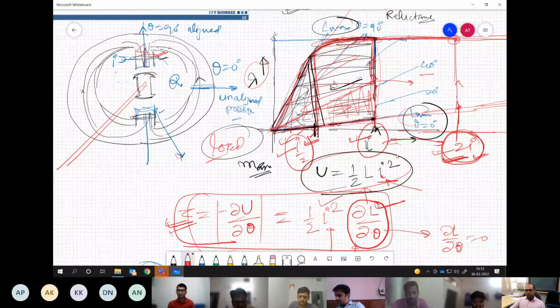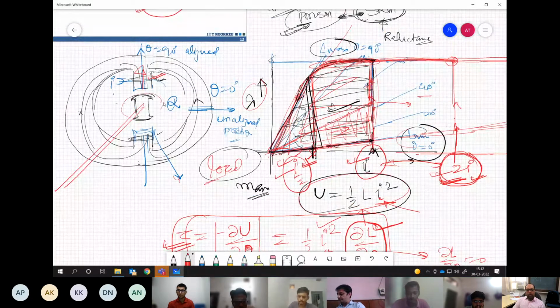And third thing, because this is a rotational plunger over here, we also need to demagnetize it quickly. So if we move deep into the saturation, it is difficult to come back quickly to zero. So it might happen that it would apply positive torque as well as negative torque while the inductance is changing to the negative side.